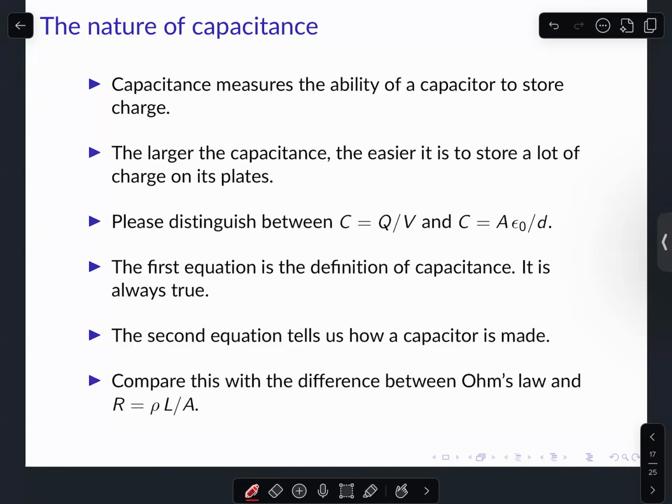In early static electricity experiments, we didn't have batteries. They hadn't been invented yet. A measure of how good your storage device is, called Leyden jars, a primitive capacitor, is how much charge you can get on there per volt being developed. Why per volt? Because if you get high enough voltage, you'll get arcing, you'll get discharge. You get a spark that would short things out, and then you've lost your charge for your experiments. So a measure of how many coulombs you can get per volt is sort of a measure of how good your capacitor is at storing charge. That's the origin of charge per volt.